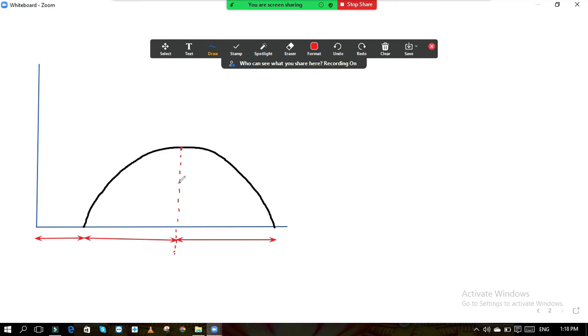Just draw this diagram. This is 126. This distance is 126. Okay. Refer to the previous parabolic diagrams which we have drawn. Those distances I am considering over here. 126. This is also 126. Okay, 0.21d, 1.42d, and then this is 348. Okay, and what is the value? This value is 3.56 Newton per mm square.